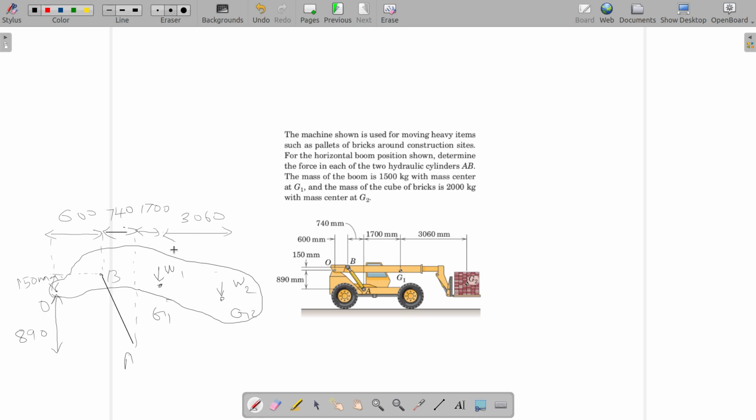Now from a single equation you can find out the member force in AB, and there are two pistons. So once you calculate member force in AB, you just divide it into 2 and you get the answer. This is very simple and straightforward. Take moment about O. Net moment about O is 0, and from this equation you have straight away the answer. So I am considering O here. So with respect to O,